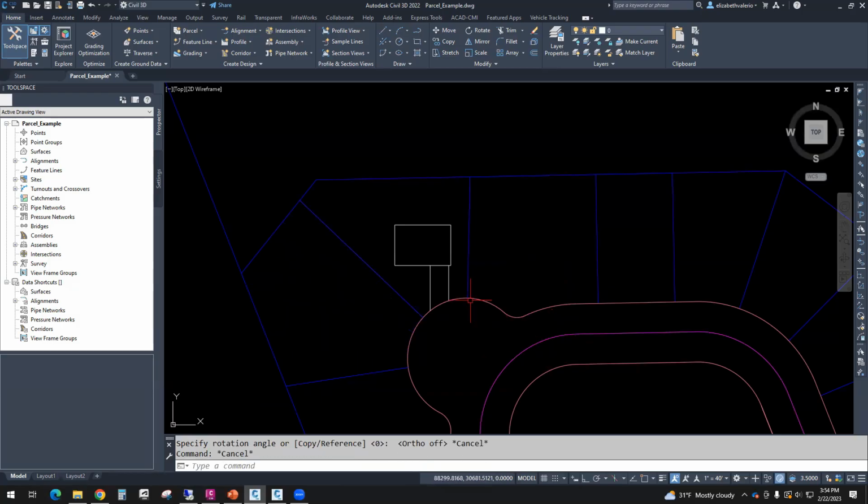So instead of forcing us to do the minimum frontage along this side of the lot, they allow us to have an offset value. Typically, the offset is the distance or length of your driveway. Once you go to that offset distance, then your minimum frontage is across this part of the lot, and that's much more doable, right? So typically, as long as you have like 5 feet on either side of the house, you're good. So the minimum frontage is now here instead of here. So this distance, the driveway, is the offset, and then the minimum frontage width is right there.